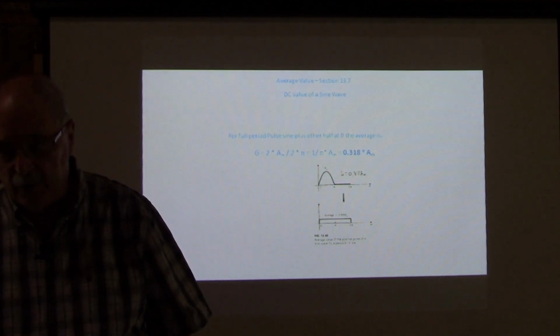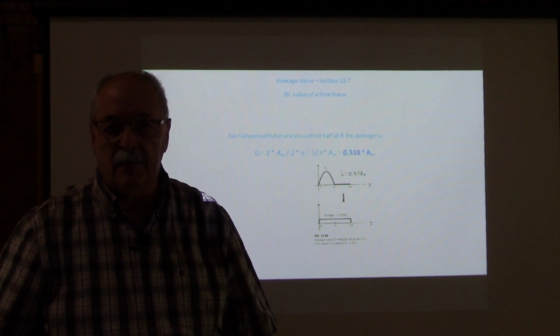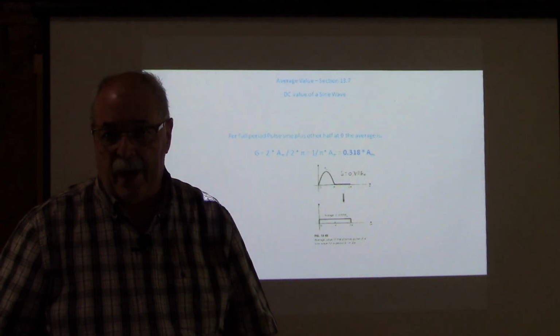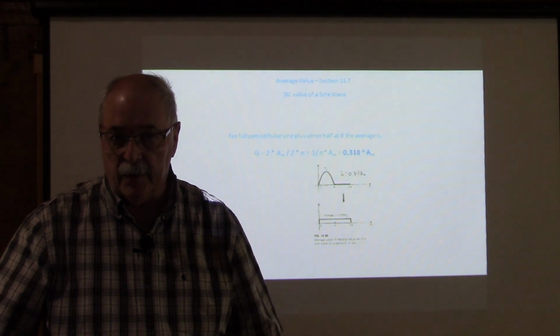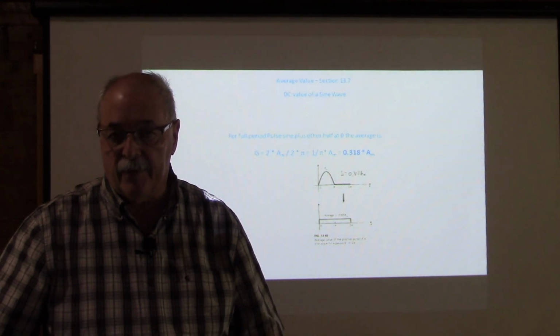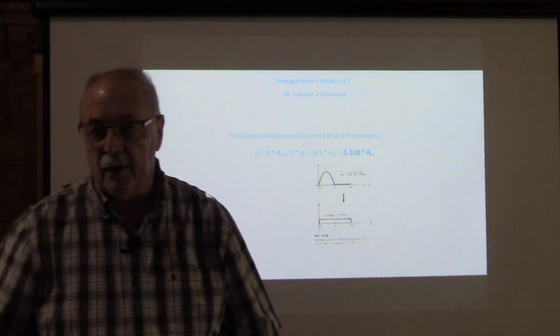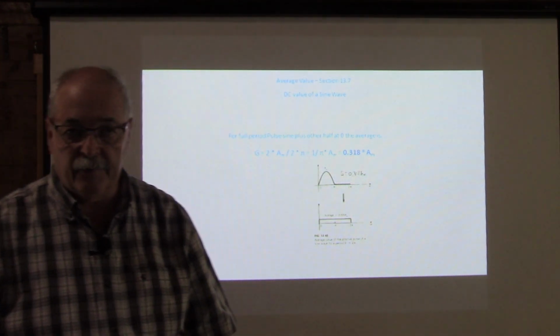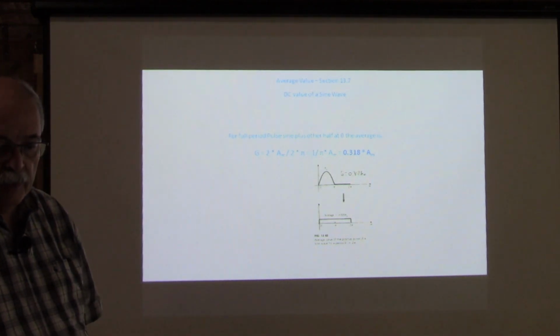It steers the current. Years ago, if you had battery-operated devices and you put the battery in backwards, it would usually blow out some circuitry. So then somebody was brilliant enough to use a full-wave rectifier on the input, so you could take the battery and flip it any way you want, and the current would always steer in the direction of how the diodes were set up. Kind of a clever way to do that. All right, that's average value.